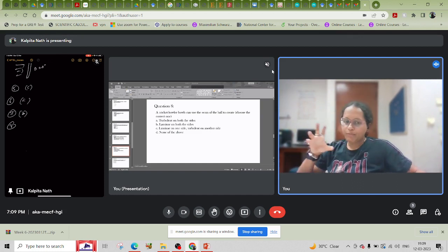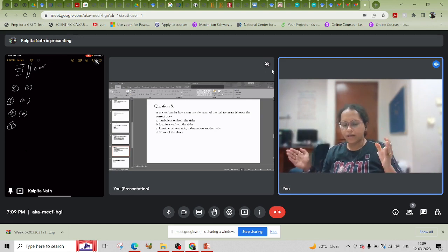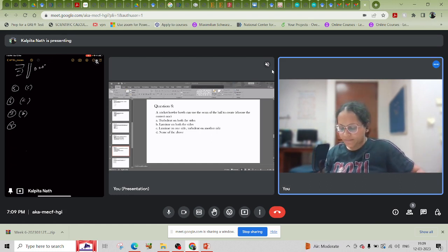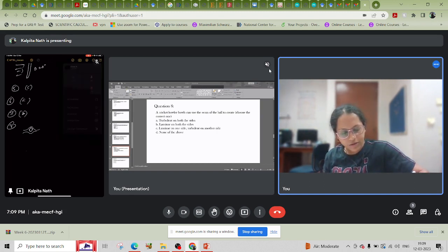So as the ball is flying through the air, a thin layer of air called the boundary layer forms along the ball surface. The boundary layer cannot stay attached to the ball surface all the way around, and thus it separates from the surface at some point.